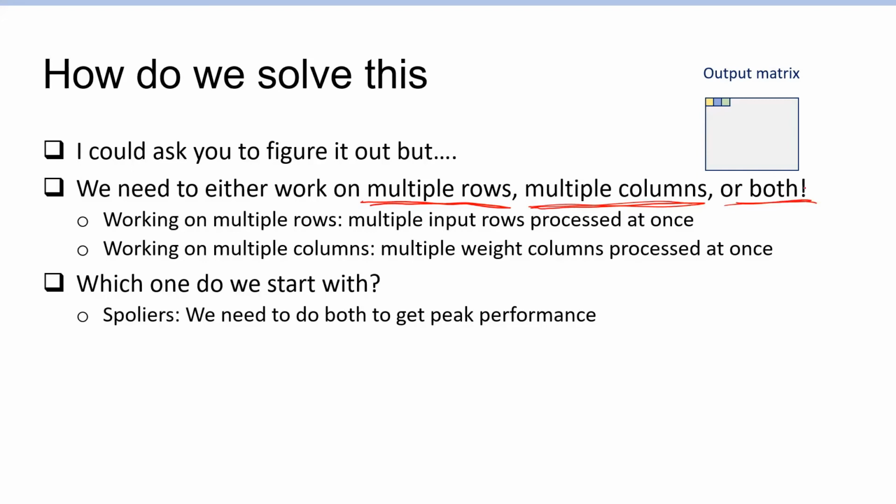That's the solution to actually solving this problem, because we need to be working on multiple independent pieces of work to have multiple independent multiply accumulate operations injected into the MAC pipeline at once, so that it doesn't have dependencies across requests, so that we can have independent operations all enqueued into the pipeline. And also across different PEs as well.